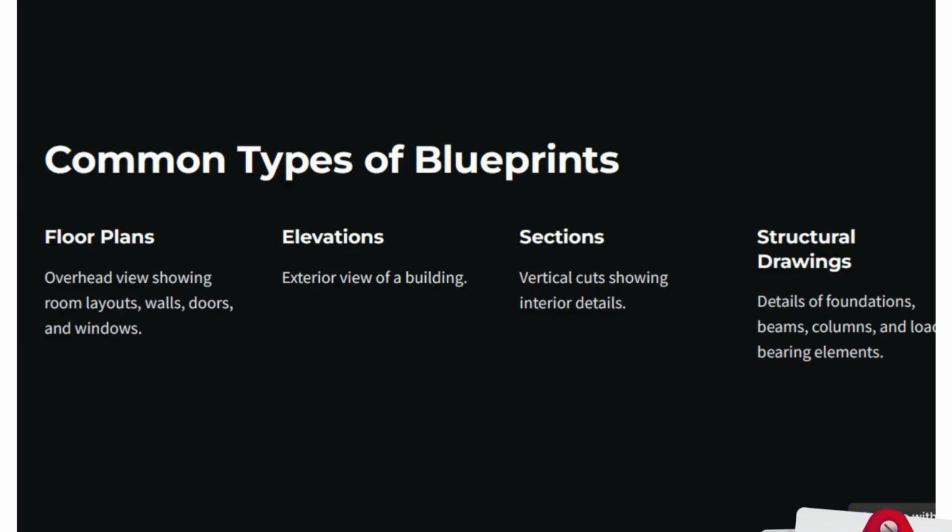It's a section for a big structural element, but in the structural drawing, the sections here are understood to be included in the details of a specific structural element. For example, the beam, the column, or maybe footing or mat. These are called sections inside the details for structural drawings, because they have their specific criteria, specific rebar, specific dimensions. You add them in the structural drawings.